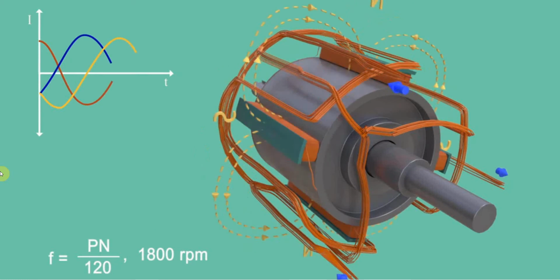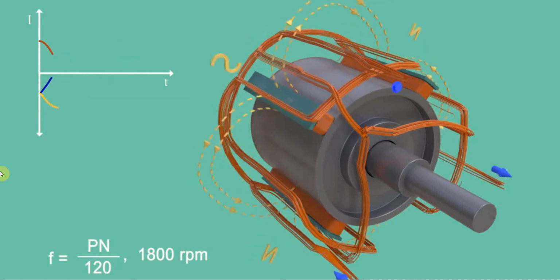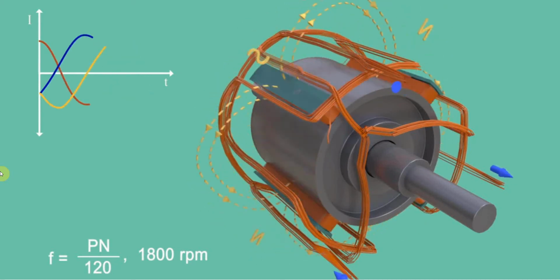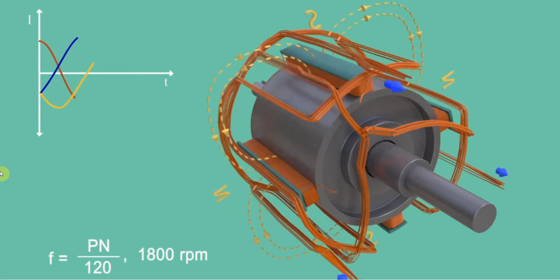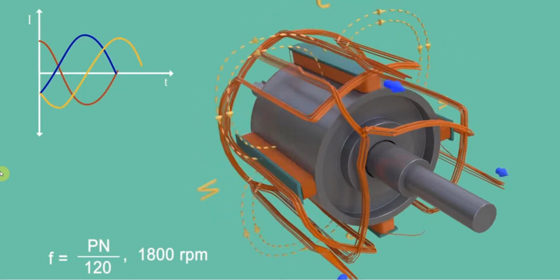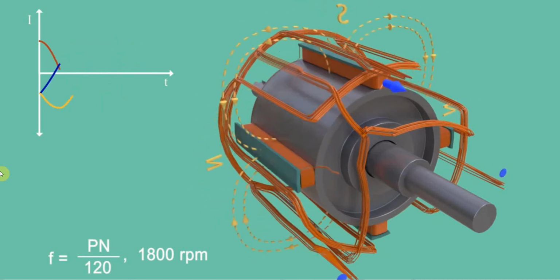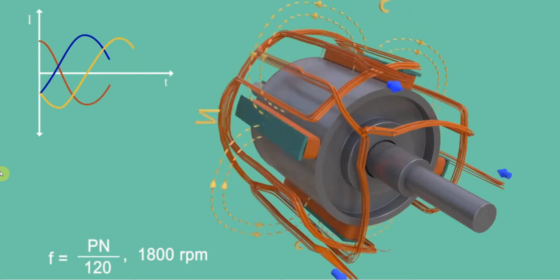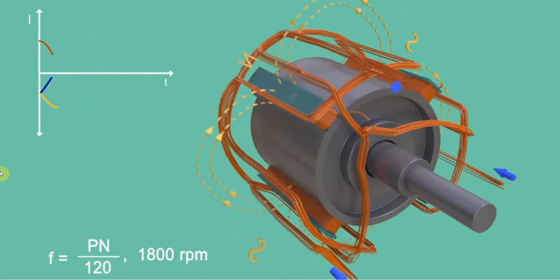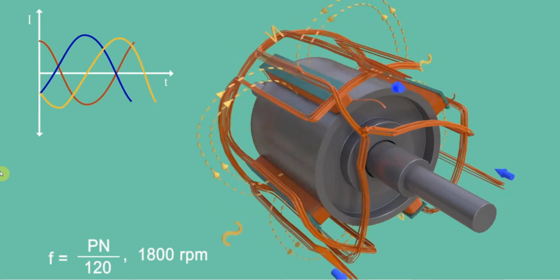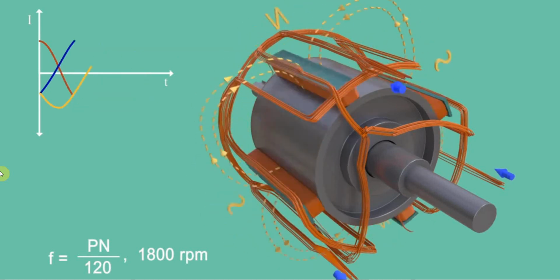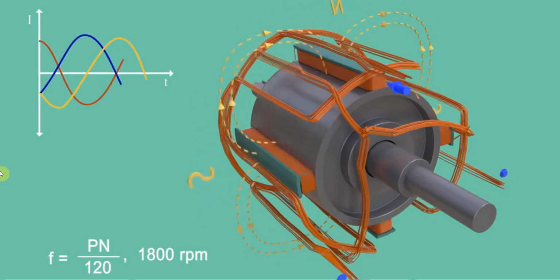Such huge RPM will induce a tremendous centrifugal force on poles of the rotor and it may fail mechanically over time. So salient pole rotors are generally having 10 to 40 poles, which demands lower RPM. Salient pole rotors are used when the prime mover rotates at relatively lower speed from 120 to 400 RPM.